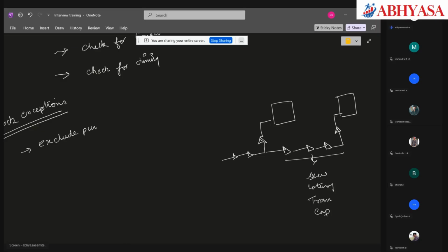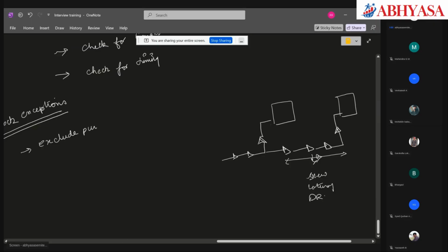Let us say I have a long net, but skew is balanced. The tool won't leave it like that. It will add a buffer. It will not allow a transition violation either. So these are the things the tool will look for: skew, latency, design rule violations. These are the things the tool will check for while adding a buffer in the clock path, and it will try to balance the skew between the sync pins.